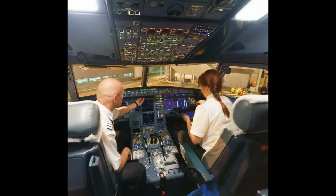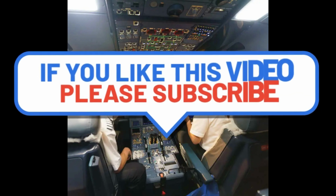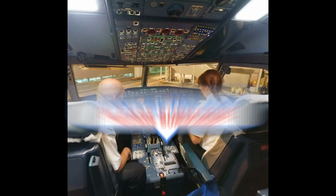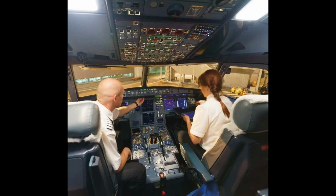Do not attempt to help the autopilot perform a task. In some instances, this has caused the autopilot to falsely sense adverse conditions and trim to the limit to accomplish its tasking. In more than a few events, this has resulted in a total loss of control and a crash.